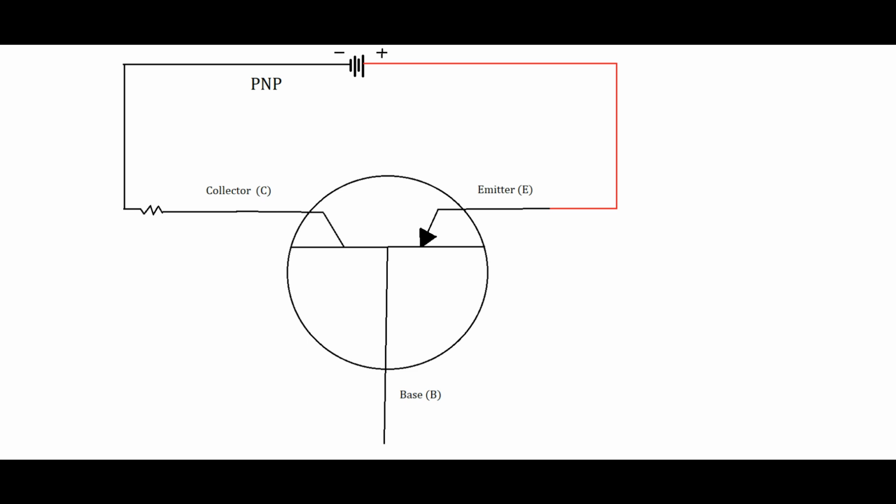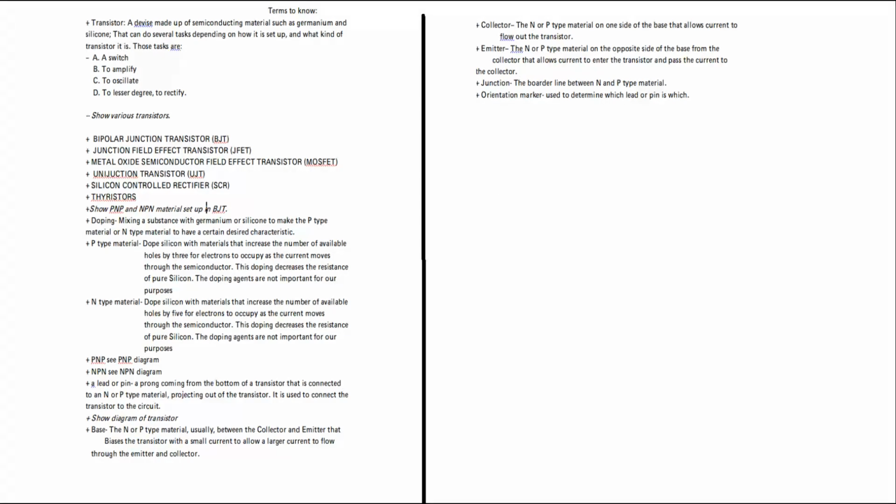One way to look at it is like a gate. The gate is closed if there's no voltage on the base. You get the base voltage, the gate opens. Now, a thing to be careful with transistors, and I have burned up transistors before, at least one, is that there's a maximum amount of current and voltage that a transistor can handle before it overheats and burns up. And the hotter the transistor gets, the more it conducts. And the more it conducts, the more it heats up. So you have this cycle. This action can keep building up until the transistor burns up.